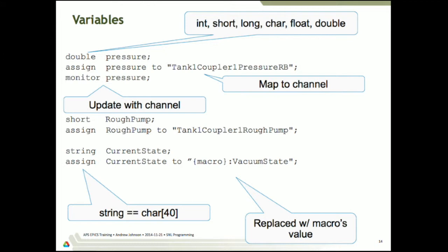And you would usually use monitors, you almost always want to use monitors on input variables that are going to affect the transitions, that cause events that trigger transitions between states in your program. But output variables, in fact, it's probably a bad idea to monitor output variables, things that you're actually generating or setting as part of this sequence program.